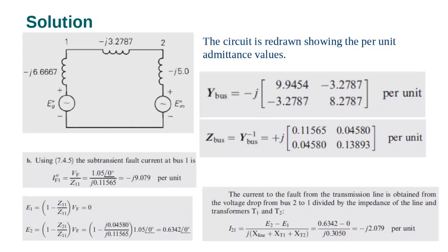All right, so it's 2 by 2. Because there are two buses, and we know how to do nodal analysis, we determine Y. So this is Y11, Y22, and remember now, Y12 equals Y21. These are equal, and you put the negative sign. Don't forget the negative sign. And then you will use the inversion.